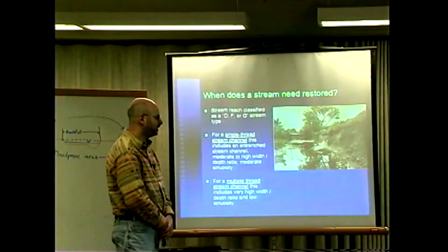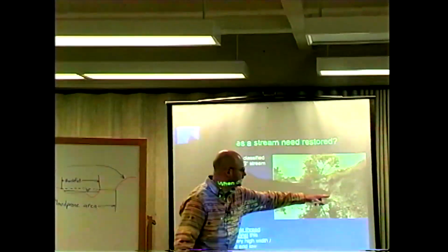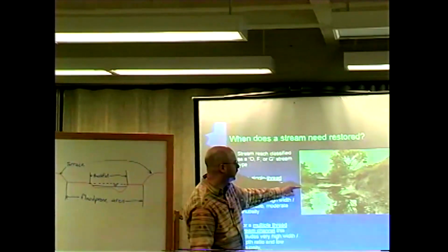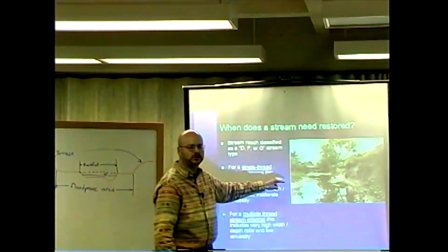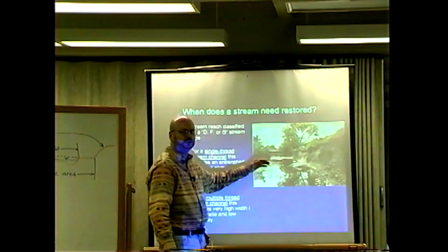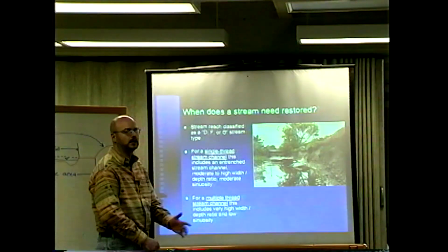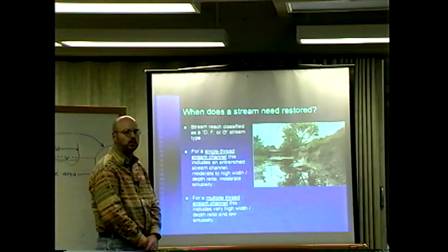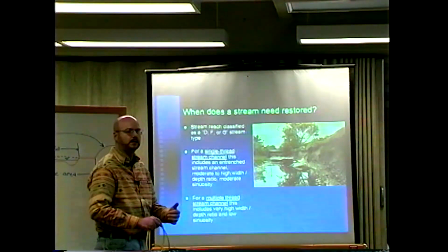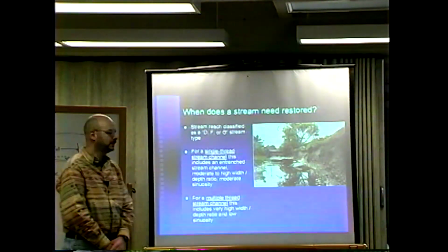The stream is entrenching. The stream at bankful probably is here to a point over here, but since there's no floodplain in this area, the stream is cutting down to try and hold that capacity of all the water flowing during storm events, because McLaughlin Run now carries more water in it than it had evolved to carry before man came.